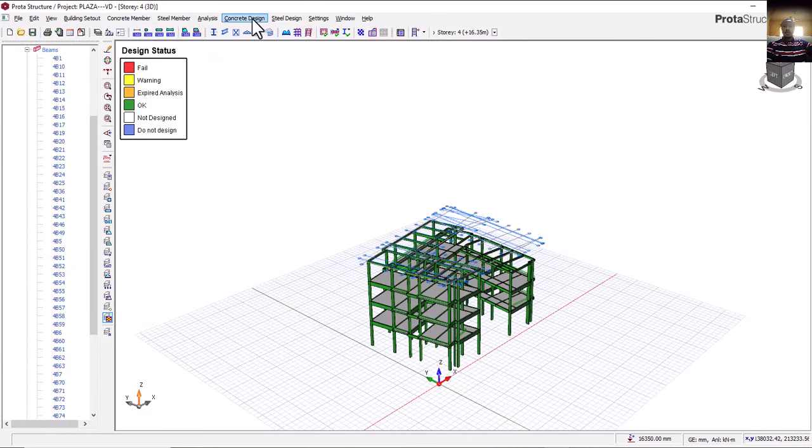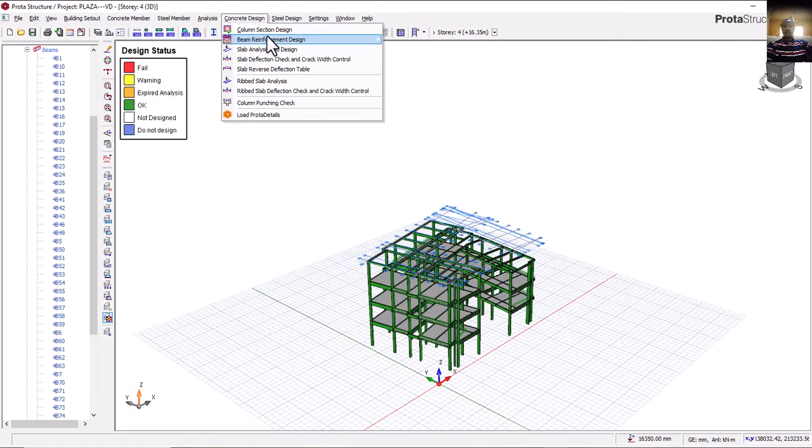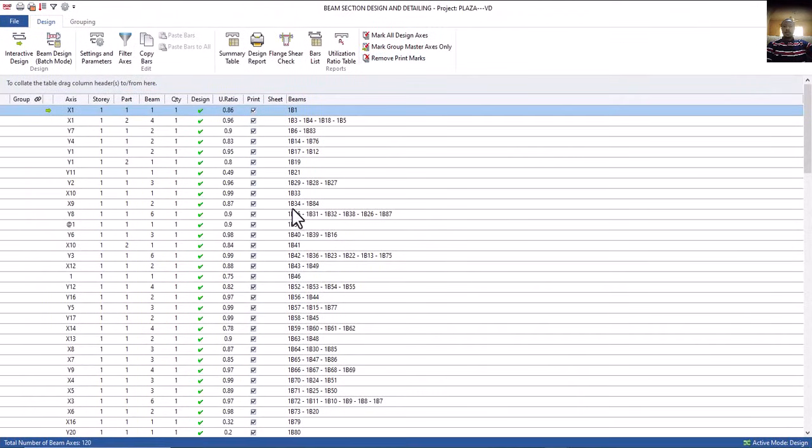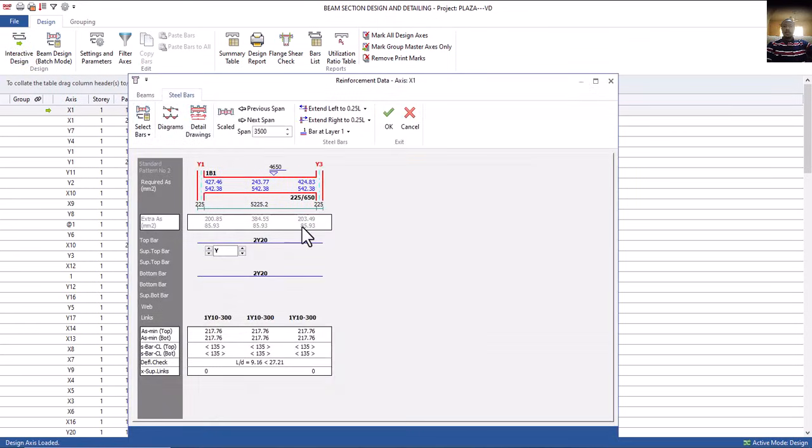So now go to this place. Come to this place and click on story beam. Is that okay? And click on this. Correct. So it's at this point that you now start your proper interactive design. Once you get to this place, number 1 check is this one, and number 2 is to make sure that this one is less than 1. Then I'll come to interactive design, and once I click on it, I'll come and check.